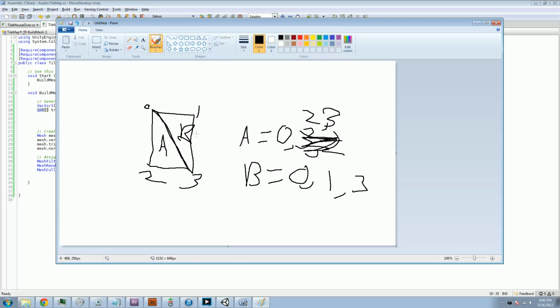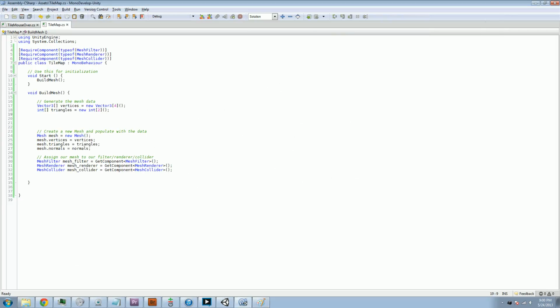The reason this is important, I mentioned this in my procedural roads video, is these triangles are only rendered one way. Only one side of this triangle is ever rendered. So if you go through this process, there's a 50-50 chance that I screw this up. If you get it the wrong way around, it's not going to be visible in the way that you want. It's going to be visible from the back side. So then you just flip a couple of these around and you get in a better shape.